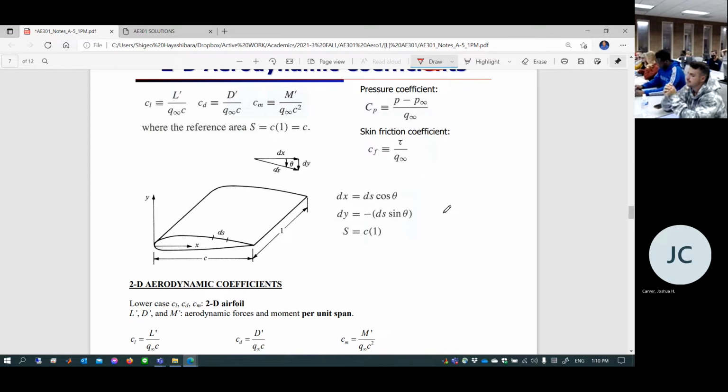The other coordinate system is, of course, starting from the leading edge toward the trailing edge along the chord. So this is X. Either X or S, you are always going to do a coordinate transformation. Here we go, this is the coordinate transformation. You have to do that all the time. One is the curved path called the streamline coordinate. Later on, if the cross-section is circular, this is going to be the polar coordinate system. The other one is X, which is Cartesian, essentially body attached, measured from the leading edge to the trailing edge along the chord.